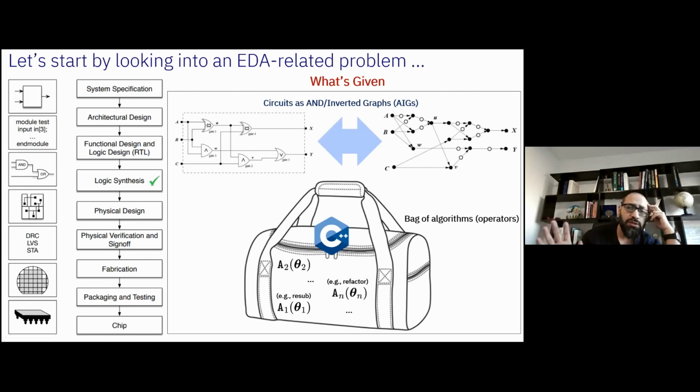But most importantly, there is a phase called logic synthesis, which will take your design and try to map that into physical gates. It will take what you thought the architecture of the chip should look like, and map that into AND gates, OR gates, XOR gates, and connections between them. And then from that, we get the physical design. From that moment onwards, we have many other steps that will at the end give us the chip.